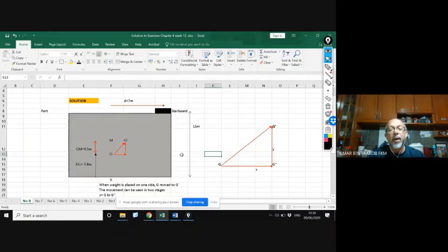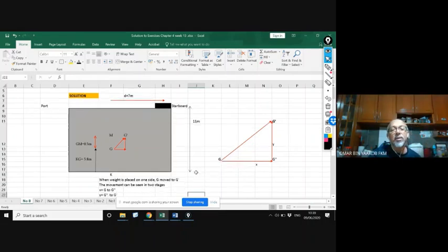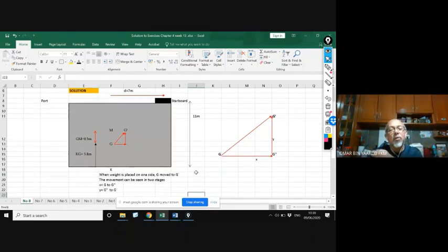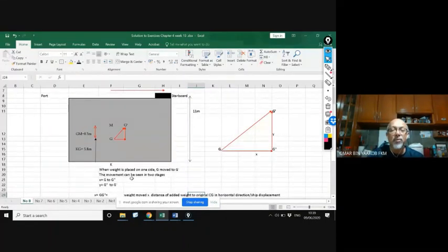So we can do that by doing it in two movements. It moves here, all right? Or it can move up here to the right. Movement to this side is because of this distance, this moment from the center line here. And movement in the vertical direction, if you take moment about keel. So in this case, we don't have to take moment from keel. We just use the formula in appendix B about movement of weight, which we have seen before.